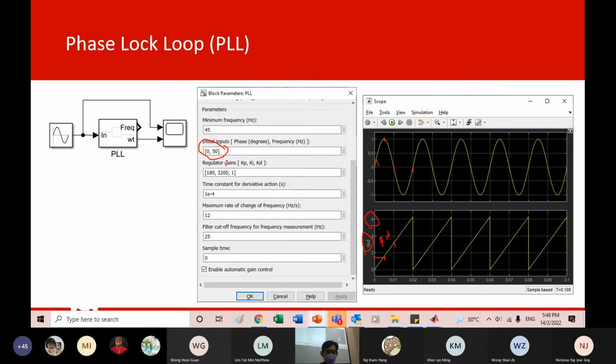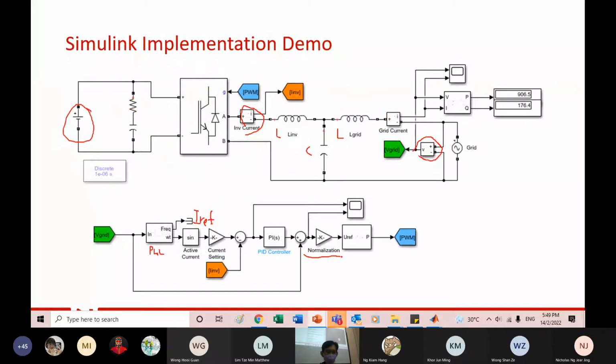Then after that, normalization, and the rest is history. Okay, the SPWM. In the old one, we needed to split the SPWM block out into 4 wires to connect. If you use this block, you don't need to, because internally it connects for you. So you just need this line to connect to this PWM, and it will switch for you.